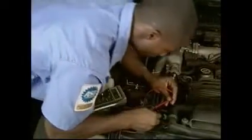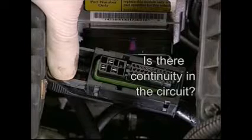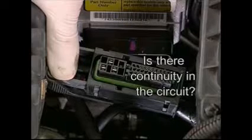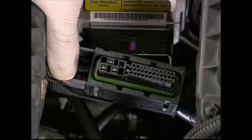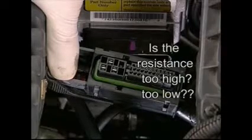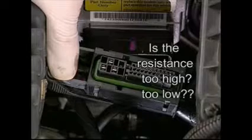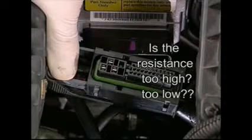The use of an ohm meter will allow you to answer the questions, is there continuity in the circuit? Continuity means that there is a path for the current to flow. A lack of continuity means that the circuit is open at some point and current cannot flow. Is the resistance of the component too high or too low? Resistance in the component affects current flow through the circuit. High resistance causes low current flow. Low resistance causes high current flow that can cause a fuse to blow.